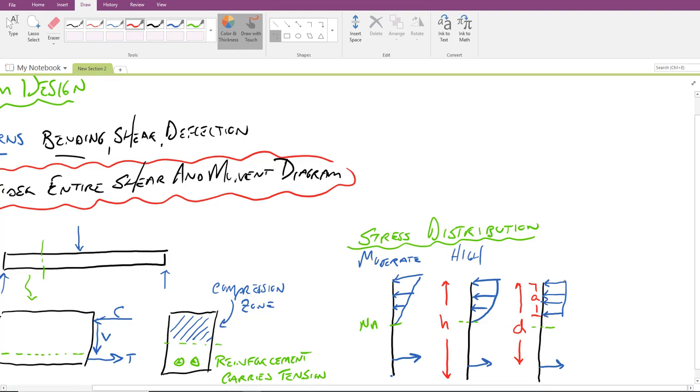As far as the magnitude of the compression block, over here we know the maximum would be our compressive stress. There are some adjustments in there, so it usually has this little apostrophe on the end of it. But because we're using an LRFD approach, that's again where we take the failure mechanism and we lower that value some.